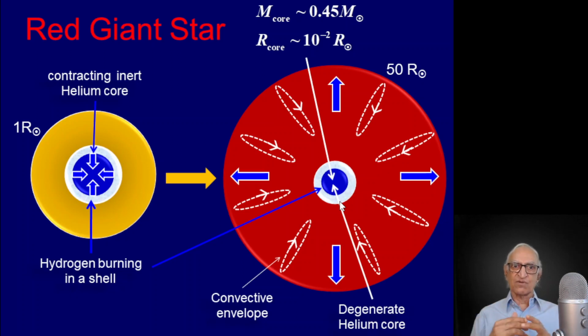It's an extremely important phenomenon, but perhaps in one of the later lectures we shall digress for a few minutes to understand why suddenly convection occurs. Very briefly, convection occurs when the temperature gradient increases above a critical value. If you have a pot of water and you put it on your stove in your kitchen and you heat it, initially the vessel gets hot and the water at the bottom gets hot, and that heat is transmitted upwards